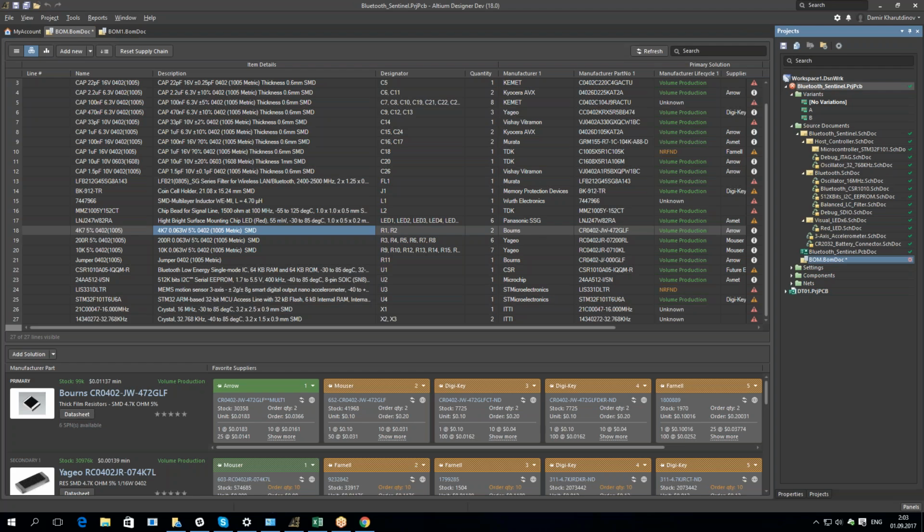From now on, if in your design you have an ActiveBOM document, that would mean all generation, in all the places whenever you touch bill of materials, will be sourced from this document. It doesn't matter whether you put a BOM table in a Draftsman, or generate your Excel files through output jobs, or you're running a BOM report just to see or do some research, that will be sourced from the ActiveBOM. If, of course, you have it in your document.